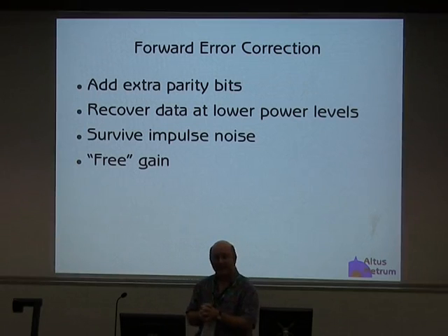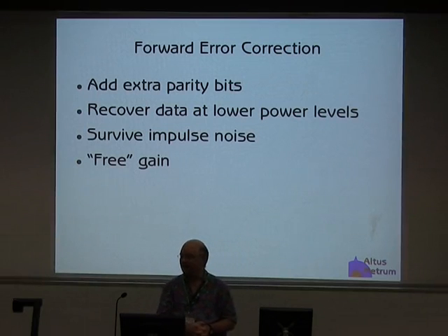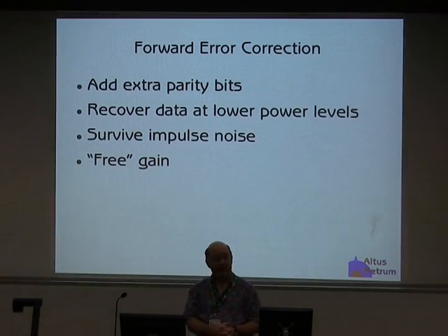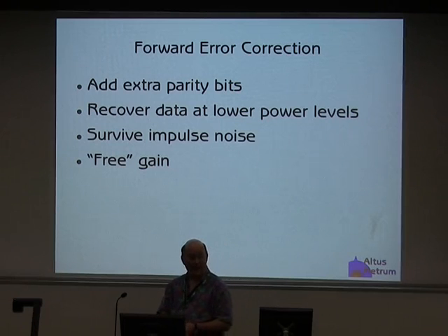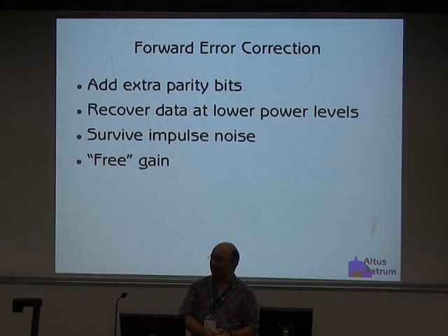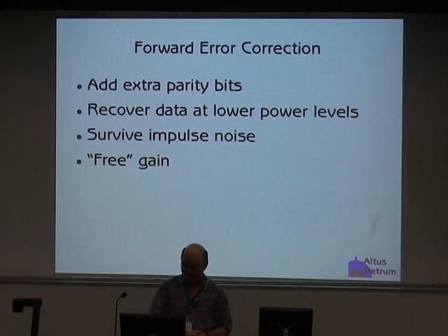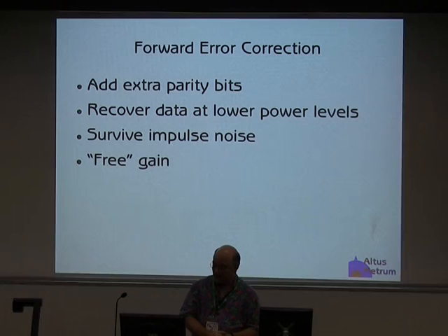So we all learned that the radios you can buy do Gaussian frequency shift keying, and it works okay as long as you have a signal-to-noise ratio of better than 10 dB. If you don't have that, if you're in a much weaker signal environment, you want to use direct sequence spread spectrum with binary phase shift keying. Pretty simple. Now I want to talk about forward error correction.